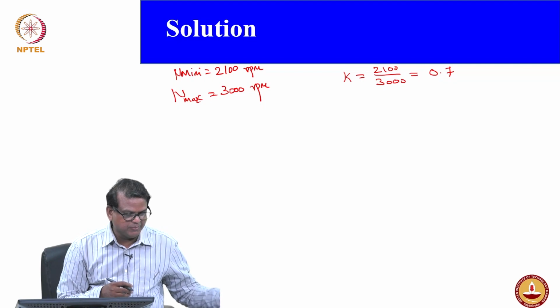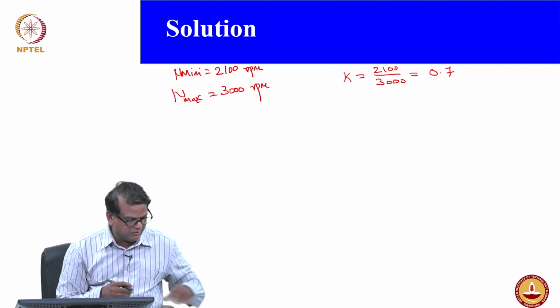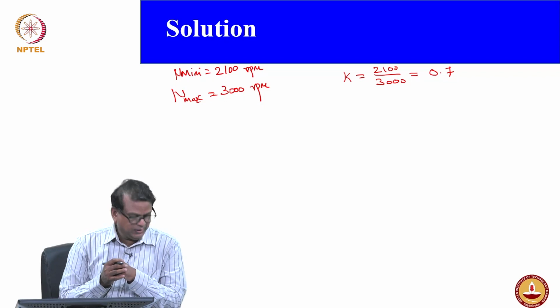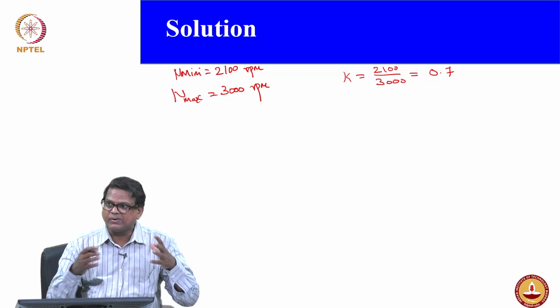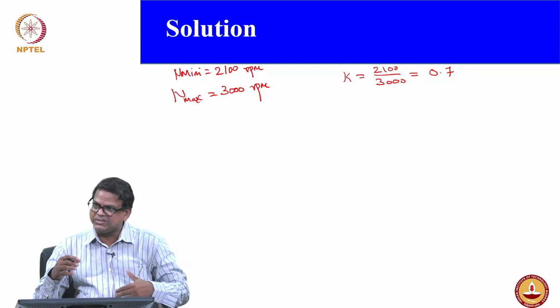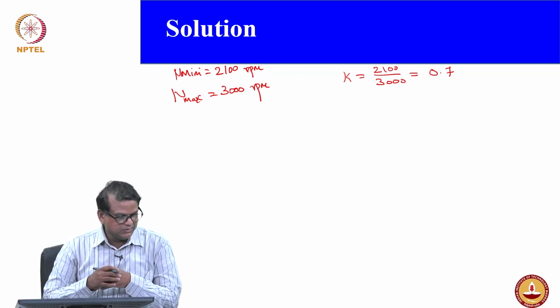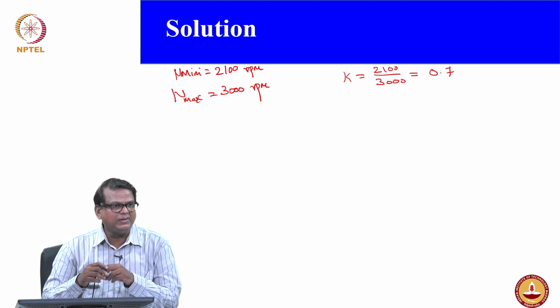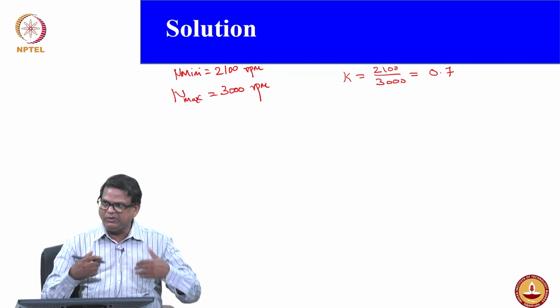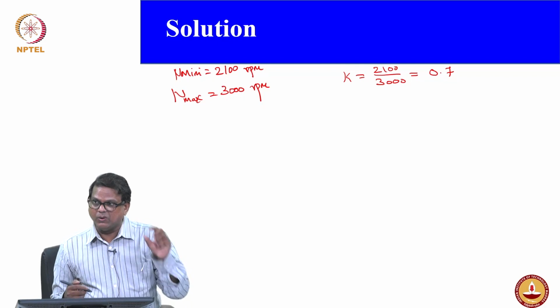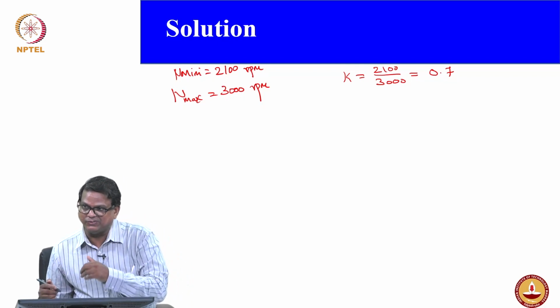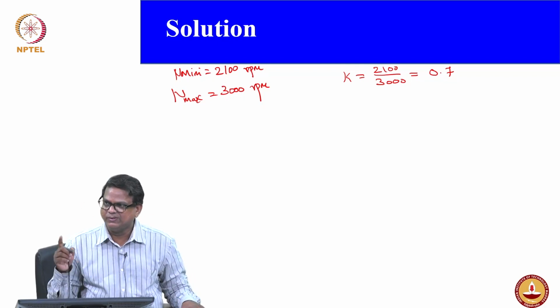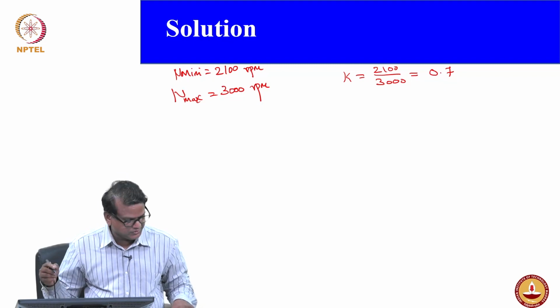So, what is the first problem? The first thing we need to find out is the overall ratio. Top is given, bottom is given. What is the top value? Top gear is given what? 4.8:1, that is the top value. The bottom value is this 20:1, both are given. So, now we need to find out the individual overall speed ratio for each gear, overall final drive ratio. Okay.